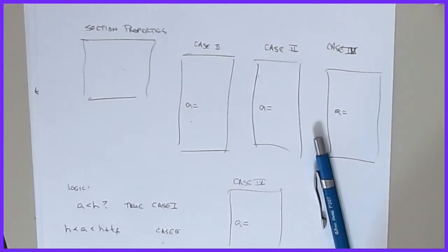And then I run through this thing, and you can see, here's my case 1. Is the plastic neutral axis in the slab? This is the A less than H case. I calculate CC, the tension in the flange, the tension in the web, the tension in the bottom, and then I figure out what my C total is. Once I have that, I can figure out their locations, because the positions of these are the dimensions of where those forces are measured from the top of the beam, right?